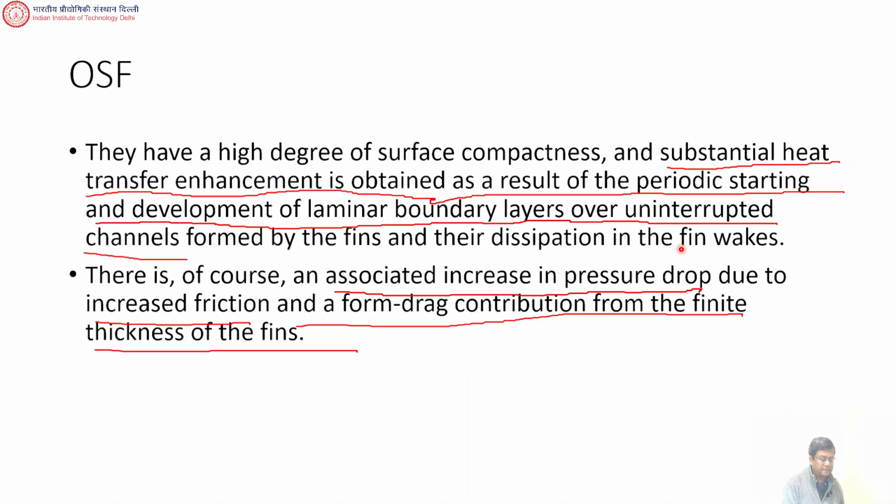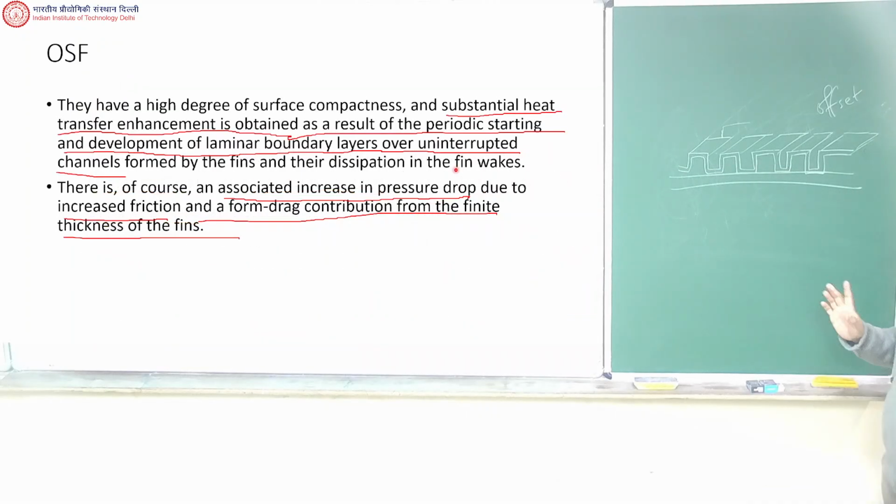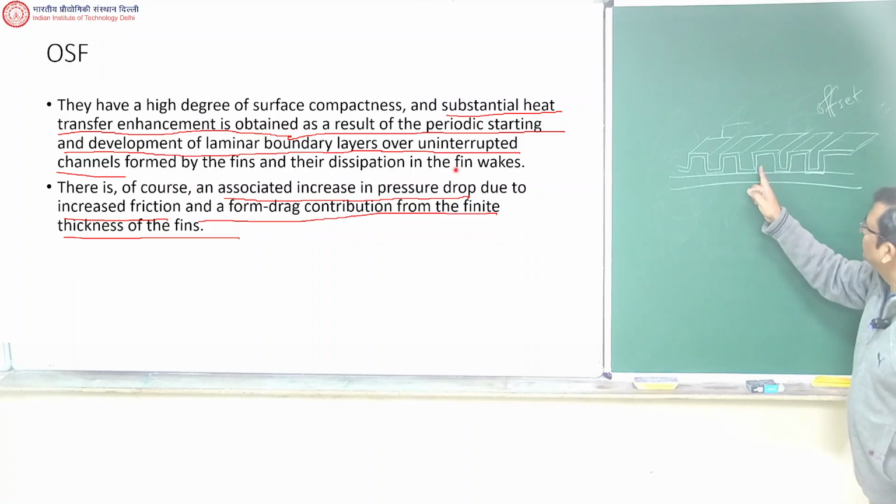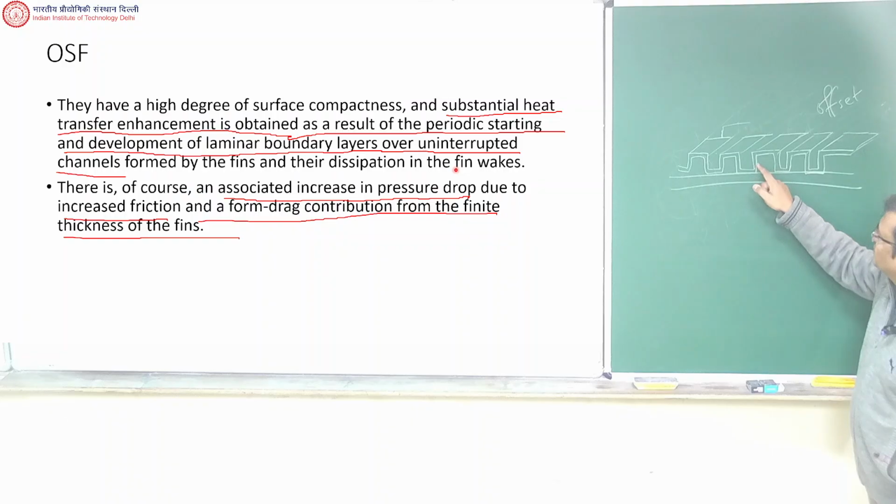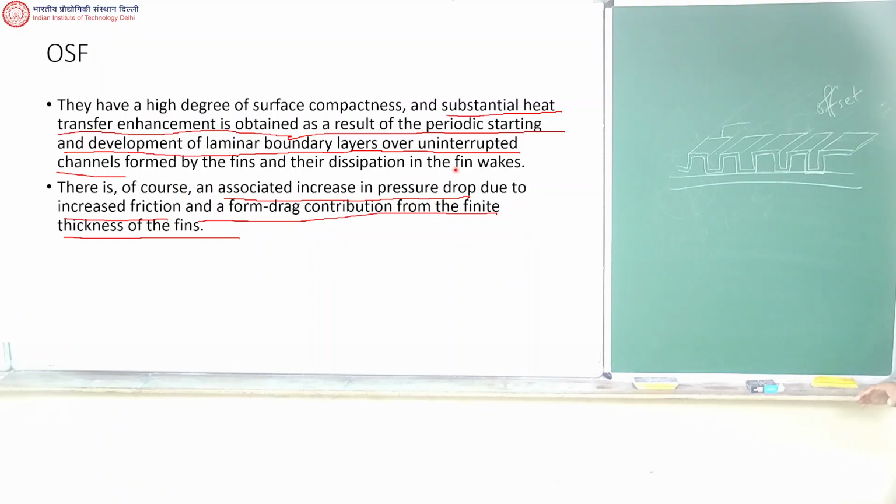And the other thing is that, as I mentioned, the fluid goes through this, right? This is the face of the heat exchanger. So you will have a boundary layer developing. Okay, nobody will argue with that, I'm sure. The boundary layer will start developing here, right? This side boundary layer. But the boundary layer will get disrupted because it will only develop up to this place, and then because of the offset, it again faces an obstruction. Then there will be disruption of the boundary layer.